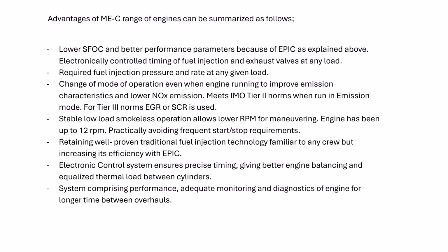Okay, lower SFOC and better performance parameters because of EPIC: lower specific fuel consumption, better performance, smokeless. SOx emission, of course, is controlled by sulfur content or the exhaust cleaning system, but NOx emission, all engines meet Tier 2 norms.